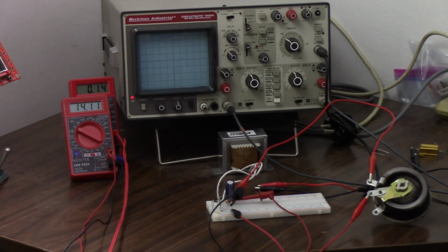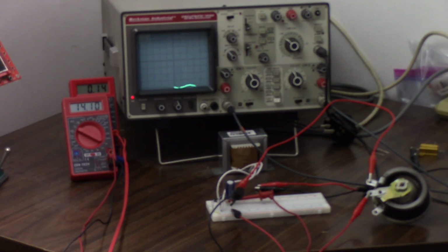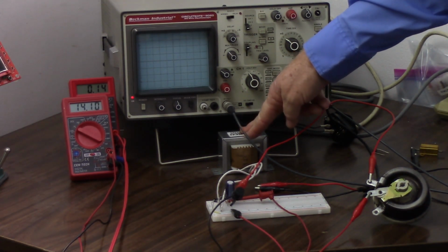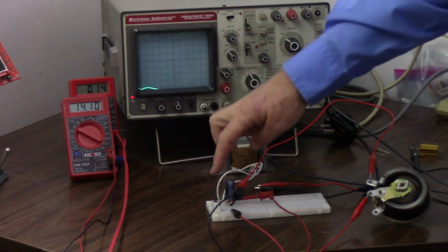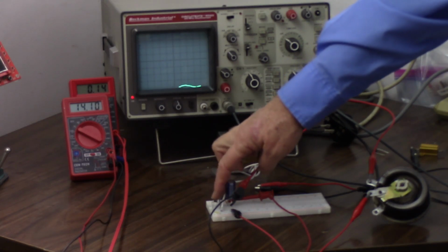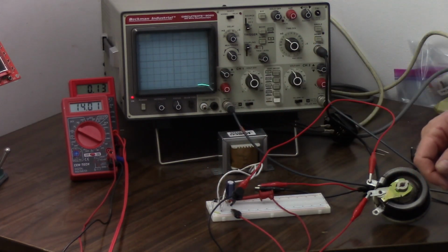So what went wrong with my thinking here? Well, what went wrong is I was just being quick and dirty about it. I knew I would have to have some voltage overhead, and I was thinking 4 volts ought to be enough. I want 12 volts out. I'll get 16 volts peak out of my transformer. That should be enough. Obviously, it's not. And the transformer's up to the task, but these diodes are not working as expected. So what's going on here?